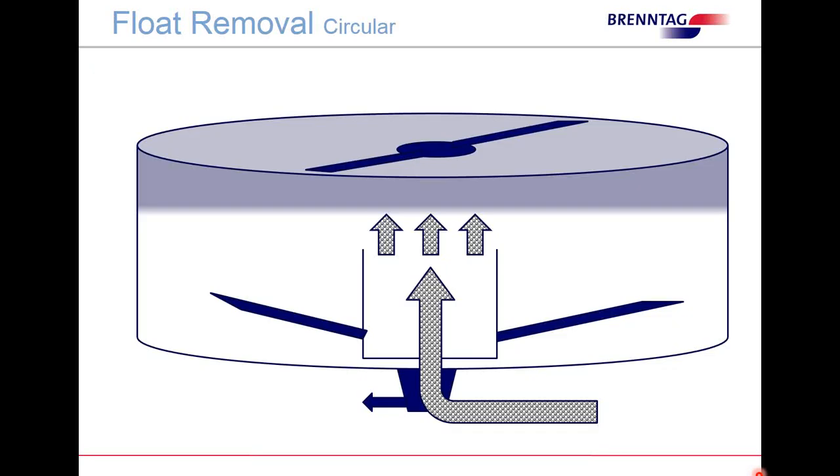So now, just to talk about the depiction, a basic understanding of a circular DAF. The water and air mixture comes into the center. It rises to the top. Here at the top, there are rakes that remove the skim. If anything settles to the bottom, there usually are rakes in the bottom, which remove the material from the bottom.